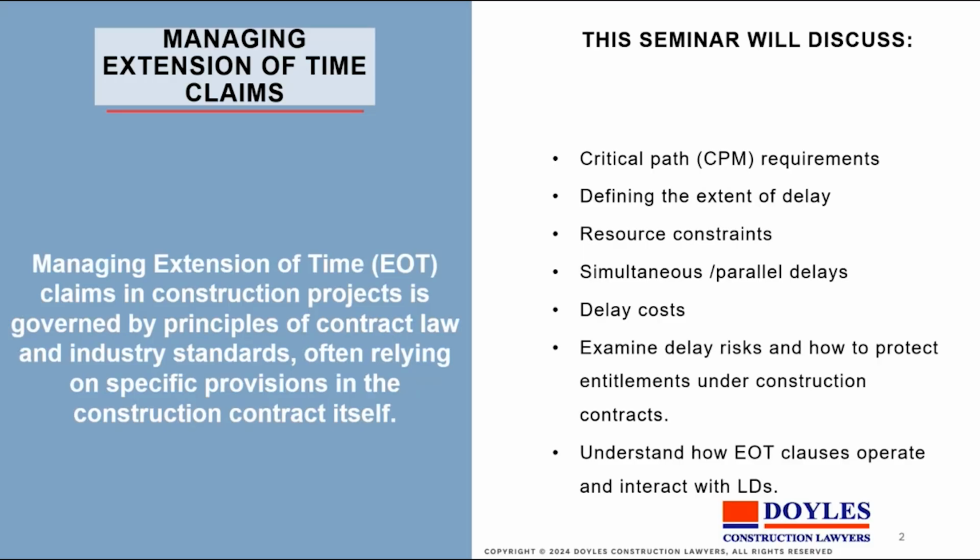The overwhelming delays and extensions of time are analysed under the critical path method analysis, but that's only one model, and although it's popular, sometimes it needs sophistication and sometimes it needs a different model to apply. So while one deals with extensions of time, one then has to have a model in which to measure the extensions of time, and those models can vary.